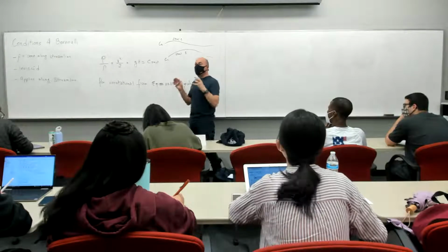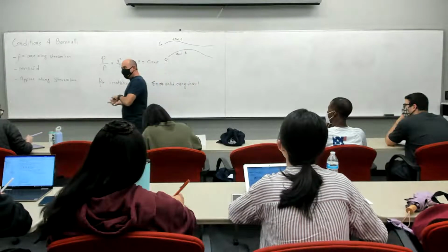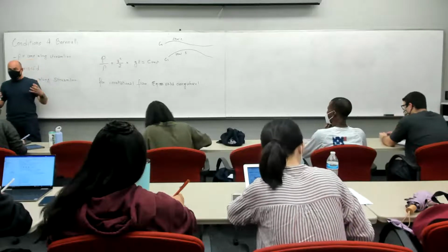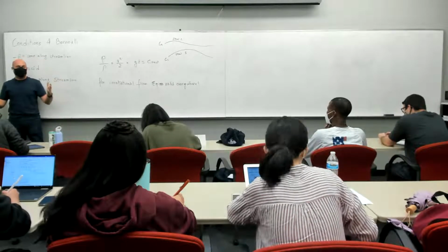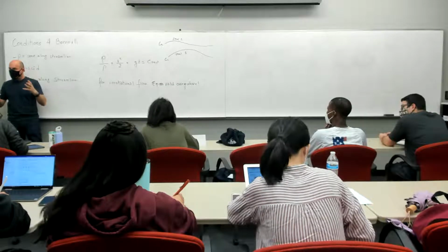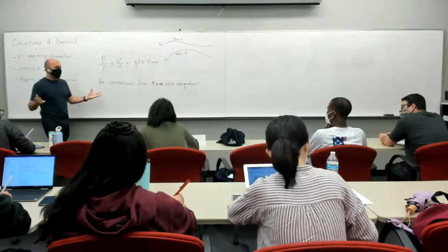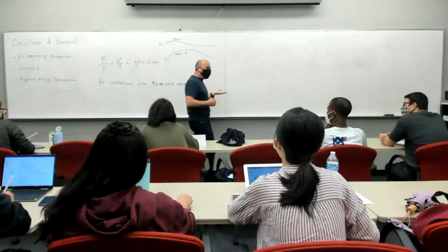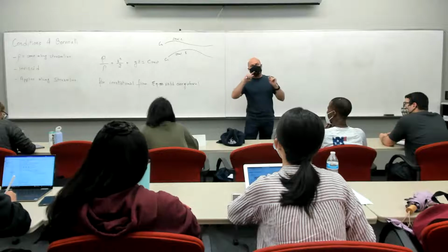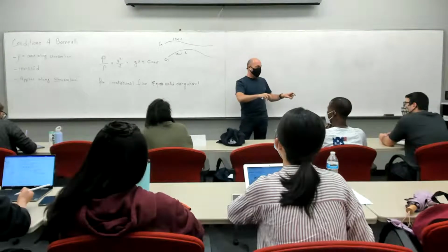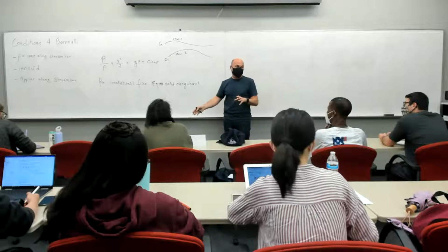It doesn't mean that the flow is inviscid. The flow mathematically can be viscous. However, the way the flow is structured, the net force due to viscosity is 0. And then you can have the Bernoulli equation. So that way, you can essentially avoid having to make the assumption of inviscid flow. You can just say the flow is irrotational.